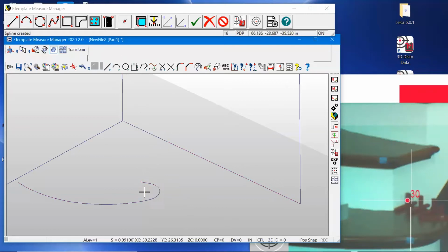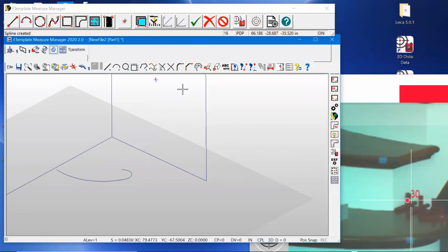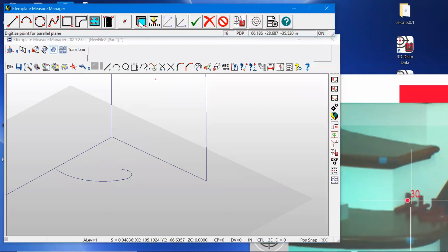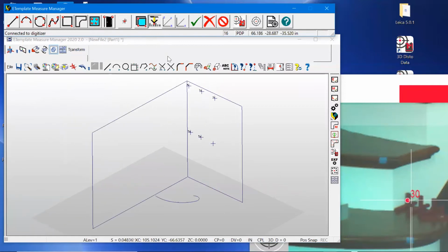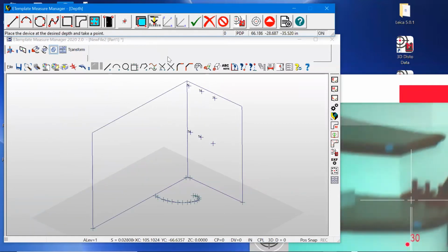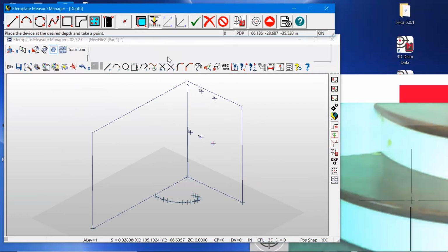Okay, so clear that. And if we go in and we highlight the spline now, we can actually delete it. And it will leave the arcs and lines version on the floor. So this is the version that we need. Okay, so we'll zoom back out, and we're going to extrude this to the height of the next step. So if I go in next and change my plane, I'm going to pick a height for this particular extrusion and go here from the floor. So I'm on top of the step.